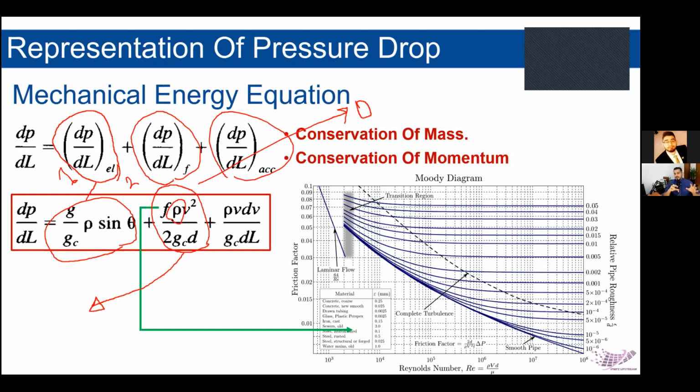It becomes challenging when you have multi-phase flowing in the well. For example, if you have water, oil, and gas, and sometimes produced solids you need to deal with. So you need to calculate a specific density that represents all of these phases. So it becomes challenging there. We have different tricks that can do that. Most of the time, we calculate the equivalent density, which is the density of the specific fluid divided by its fraction in the flowing region.